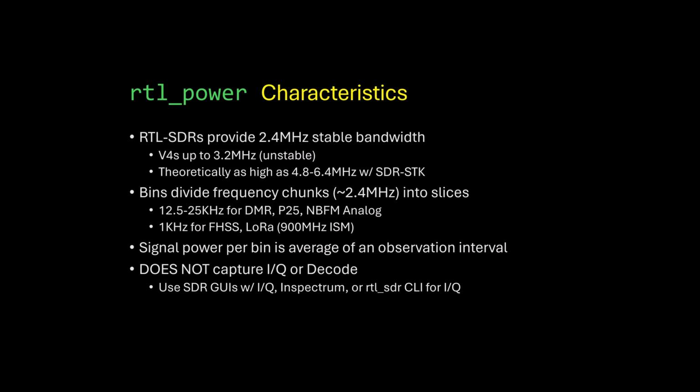If you wanted to find some frequency hopping, spread spectrum stuff from, like, mall or fast food radio intercom communications, or those funky Motorola radios that support 900 ISM, or you're looking for LoRa or some other IoT, you might want to use a much, much smaller slice like a kilohertz.